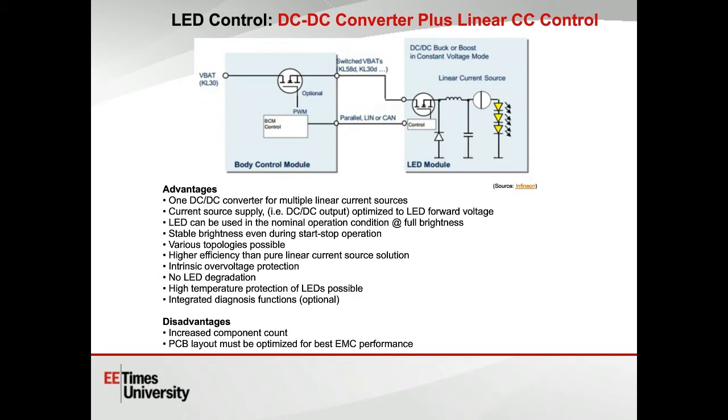And once again, because it essentially starts with a switched topology, we have to worry about EMC, electrical noise. And so the PC board layout must be optimized with a view to keeping sensitive circuitry that's susceptible to electromagnetic interference away from the switching circuitry. And if you go to any of the mainstream semiconductor companies' websites, you will find many application notes talking specifically about this problem, how to deal with switched transients and how to optimize your PC board layout in order to minimize the effects on the rest of the circuitry.